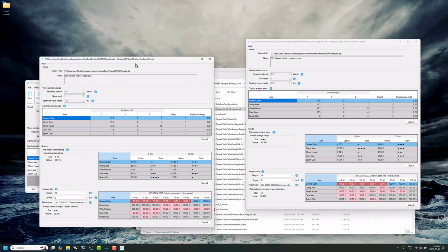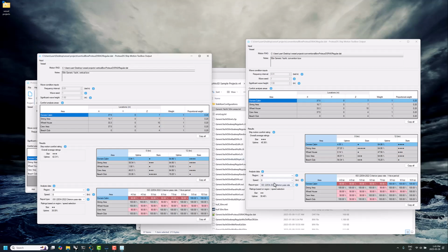There wasn't anything particularly special I had done for the hulls that I generated. There might be a smarter way of adjusting the prismatic coefficient or whatever. Obviously, you want to keep the displacement similar, but you're starting to get a difference in results, and it might give you some insight into what bow form factor might give you some advantage in terms of motion affected comfort.